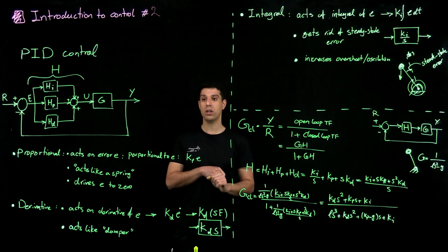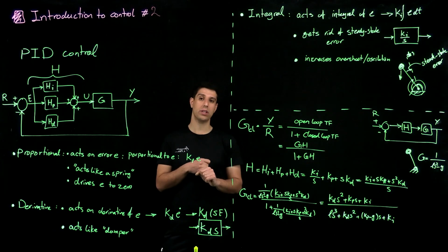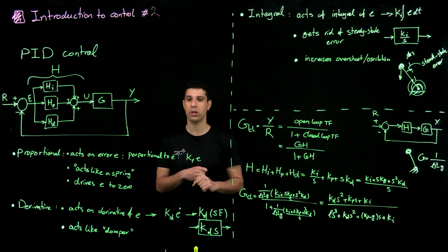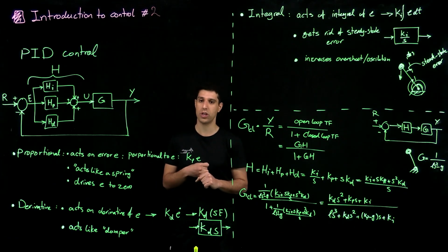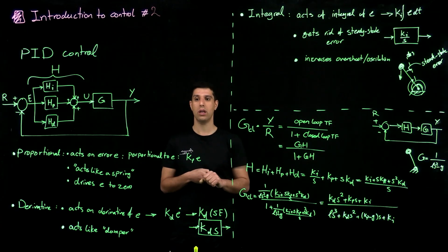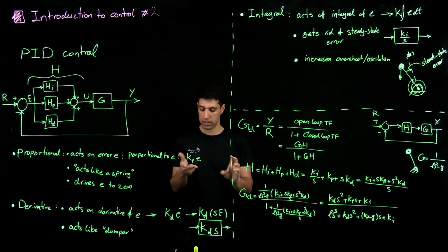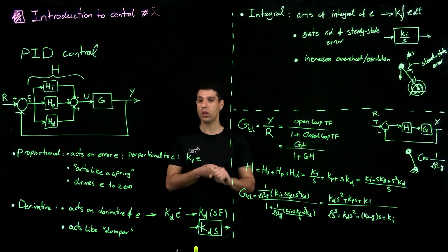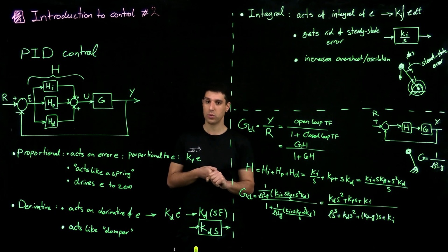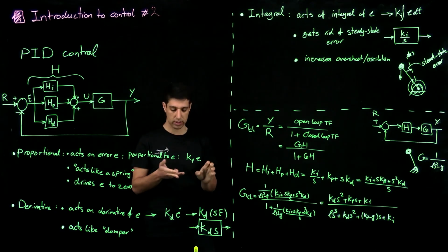The second one, we moved on to state space, which was a little, in my opinion, stronger and more powerful notation. And we used the same method using eigenvalues, which was the poles of the system, to look at the stability. We visualized the system using phase portrait, which was, in my opinion, again, a very powerful way to think about the system.